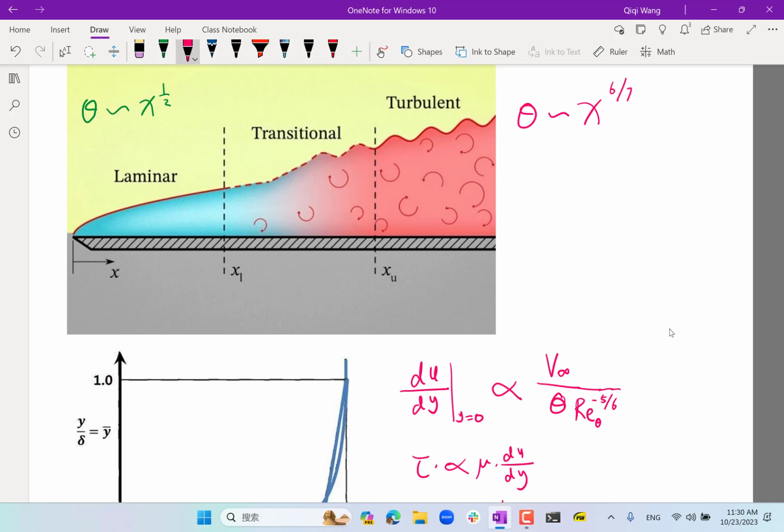So if I look at a very thin airfoil, almost a zero camber airfoil, at midspan versus the trailing edge: if the boundary layer is laminar, then at the trailing edge, the boundary layer thickness is square root of 2 times the thickness at the midchord. But if the boundary layer is turbulent, then the thickness at the trailing edge is going to be almost twice the boundary layer thickness at the midchord, even without any pressure gradient.